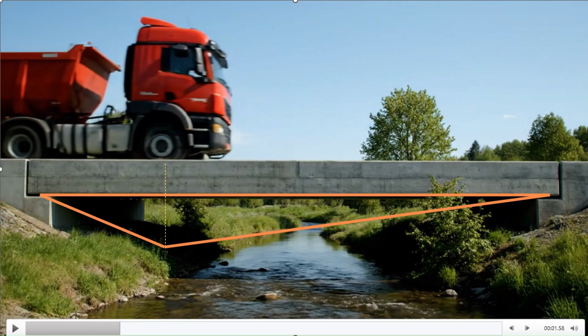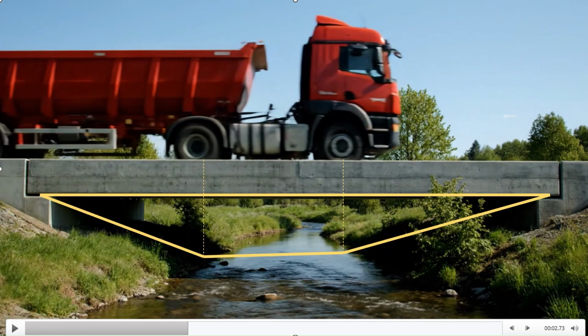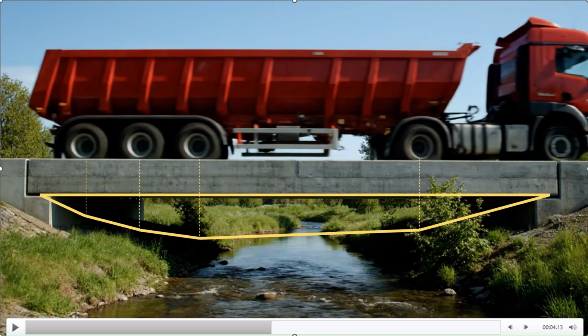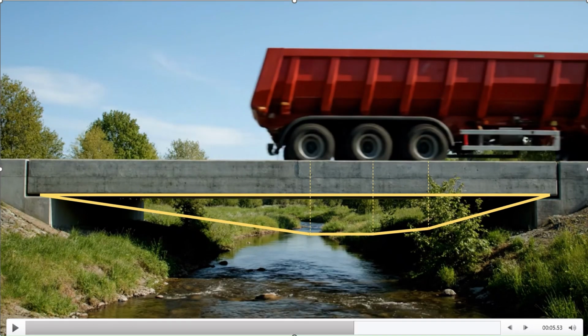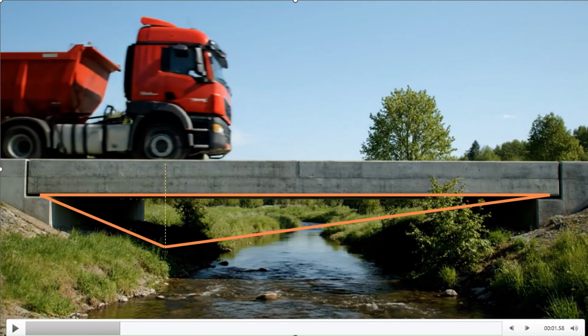So now we'll look at the bending moment from a point load. As the vehicle moves along the bridge, you'll see that the bending moment profile changes as additional axles go onto the bridge. The more axles we have, the closer we get to a curved profile. But we'll keep it simple and focus on a single point load. The same principles apply, whatever the arrangement. We're going to go through exactly the same again, but this time for a point load. We'll do it quicker because it's a bit more straightforward.